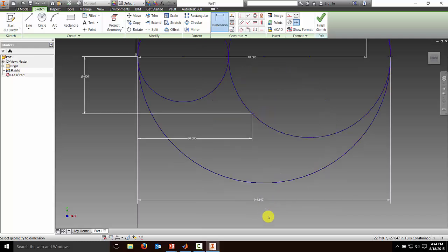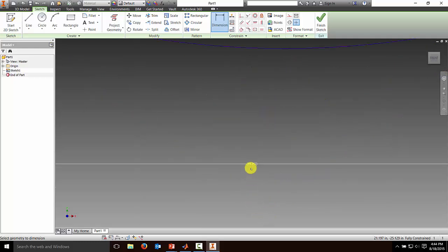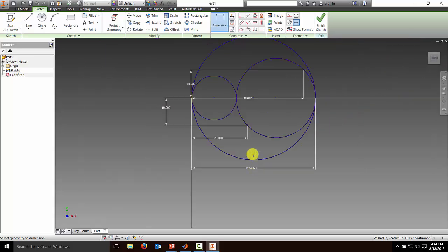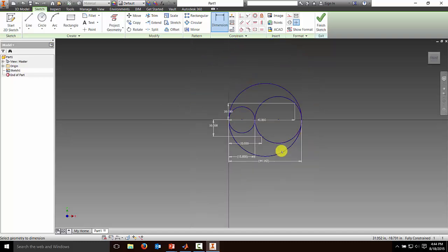It's just showing me what's already there. Notice the 44.12. That matches the value we calculated in the other two methods. Okay, so there's our 0. There's our 44.12. And if I take the dimension from 0 to point 2, I'll get the 15.58. Again, it's a driven constraint. So here are my two normal stresses. The other thing I can do is figure out what the maximum shear stress is.